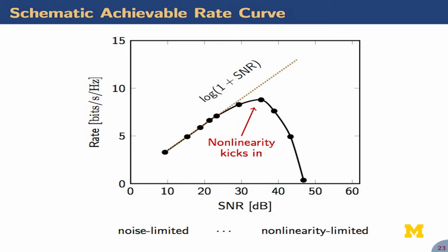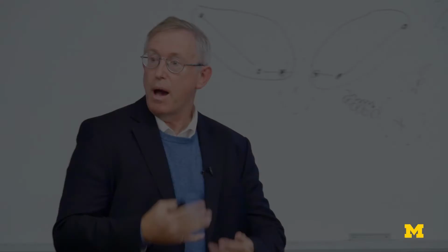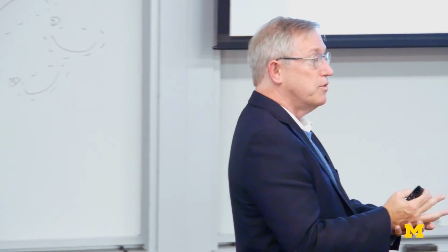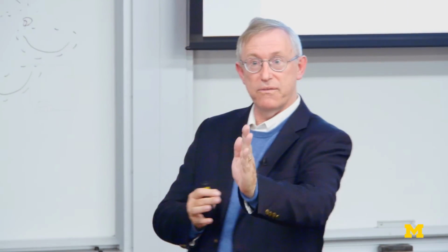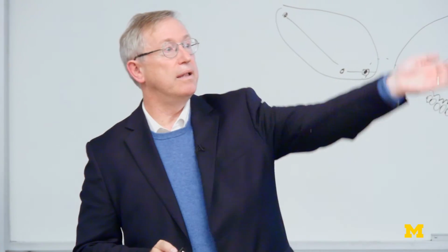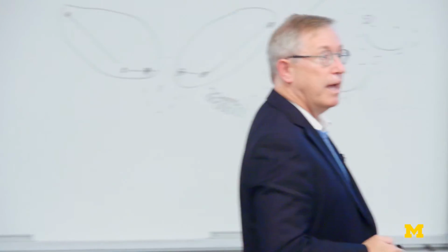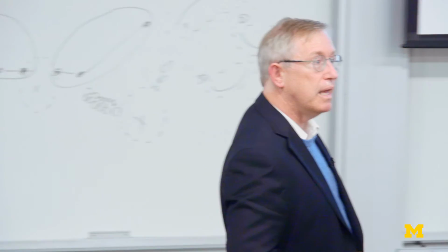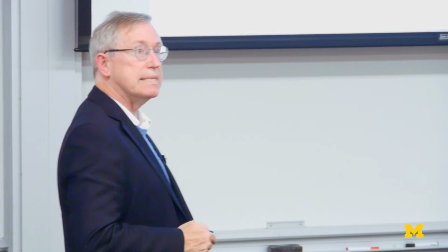So in a sort of cartoon, this is more or less how things work in this optical business. People seek this optimal launch power where they optimize some criterion, maybe the received OSNR, optical signal-to-noise ratio, and they tune the transmitter power until they find the sweet spot, and then they transmit at that particular optical power. If they go higher than that, there's too much nonlinearity noise induced, and they don't want to do that. So it seems like this nonlinearity noise is a dominating impairment in this type of transmission system.